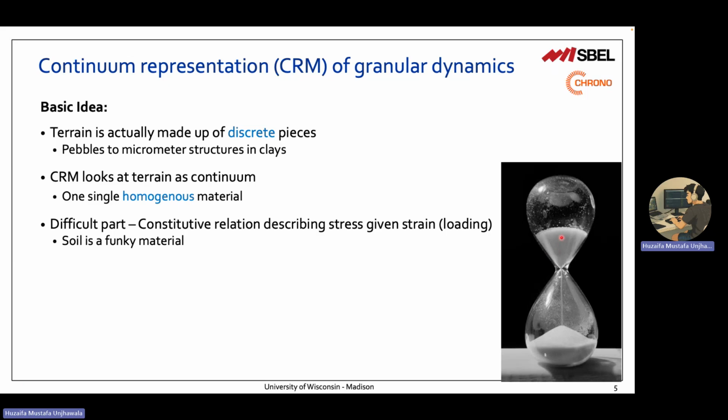So here you can see some sand falling down. Obviously I didn't come up with this example. It's a popular example. At the top of this glass, you have soil that behaves like a solid, it's stationary. It's hard to shear and hard to compress. As you go down towards the restriction or the opening, soil starts flowing, right? So it's behaving more like a fluid, it can shear, and the shear rate is some property of the internal friction. So it shears and goes down.